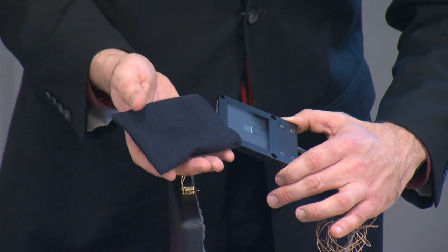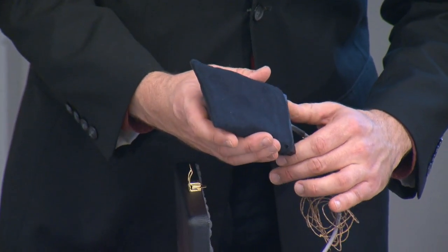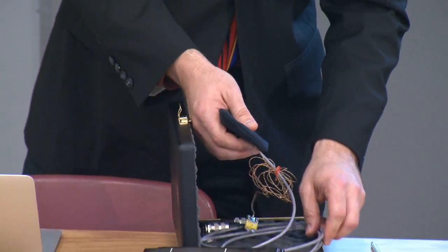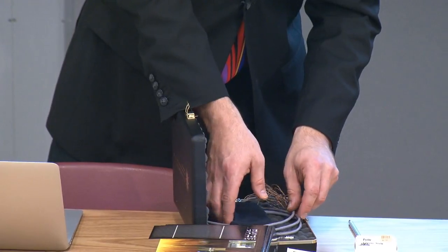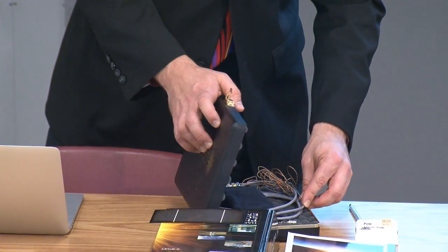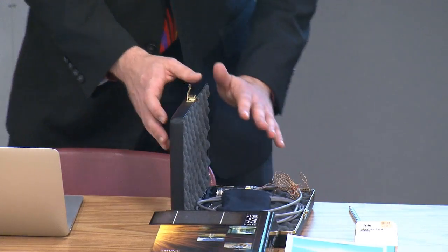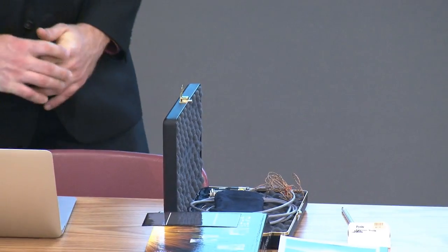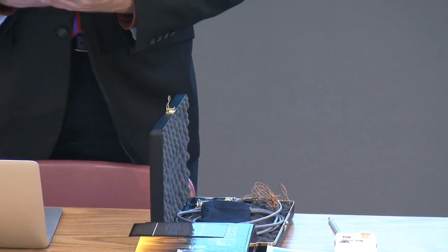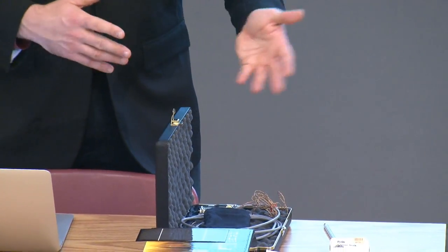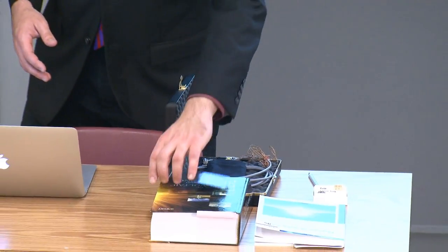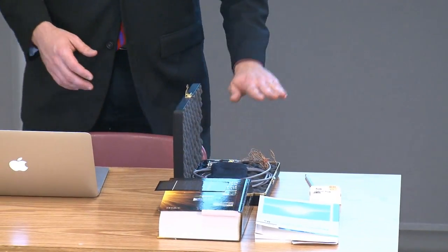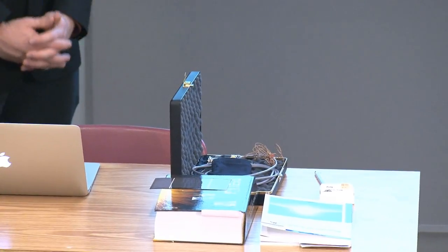It was tested at NREL. The short circuit current, open circuit voltage, and fill factor of that device are well known and reported, and it is essentially sent with that device back to our laboratory. Now, whenever we want to make a new measurement on any cell inside of the laboratory, we'll measure the reference cell first just to make sure that our solar simulator is well behaved.